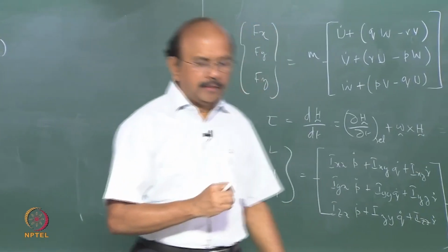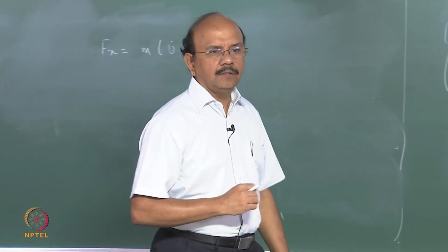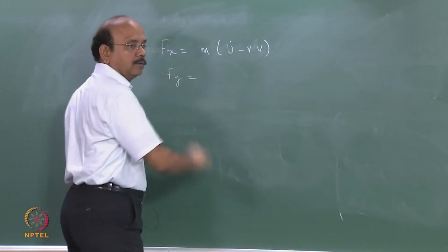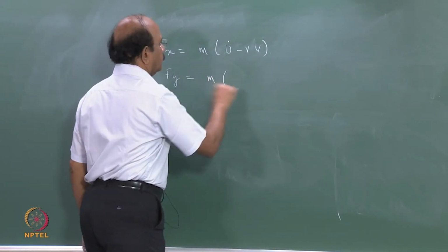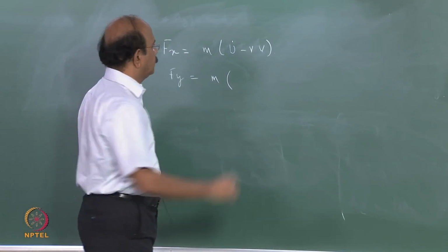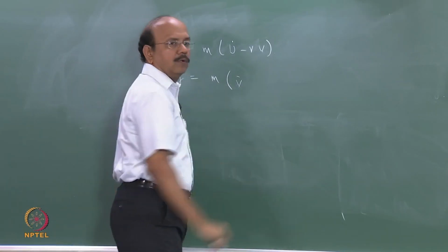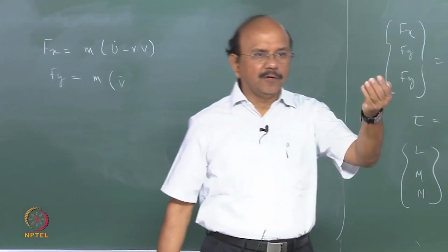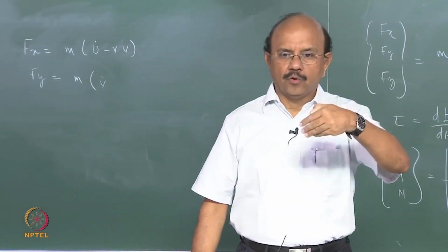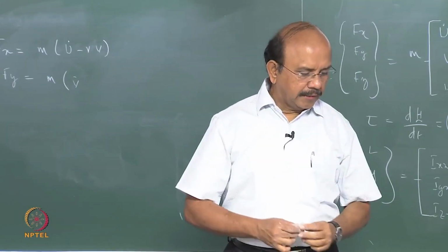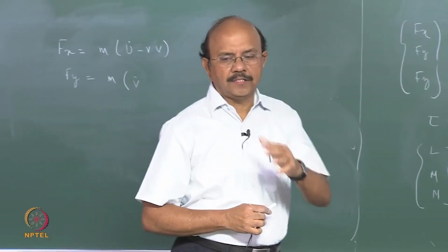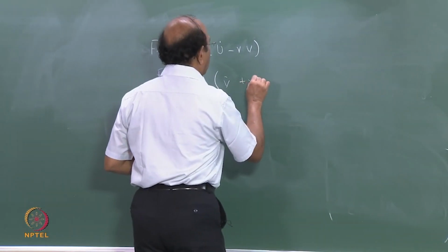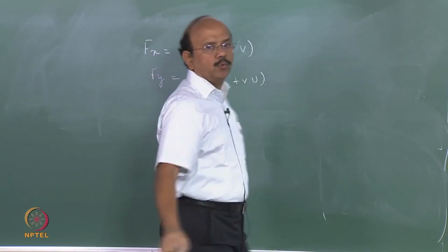Now write down for the lateral force, Fy, is equal to m into v dot. Okay, that's the first term, our relative dA, dou A by dou T. So because of which I get a v dot term. What's the next term I would get? I'm neglecting q and so on, plus r q.